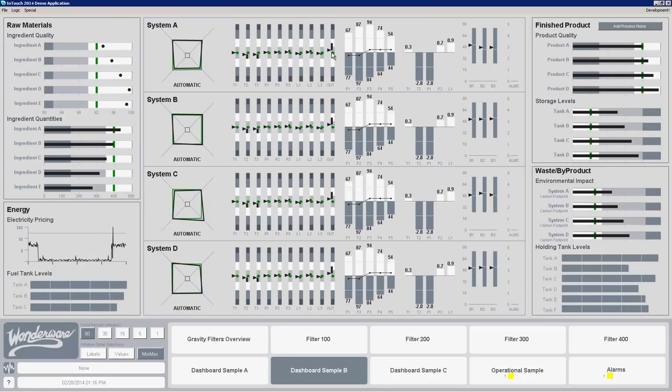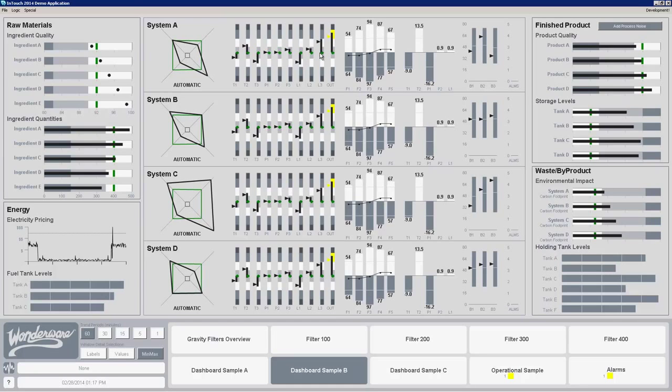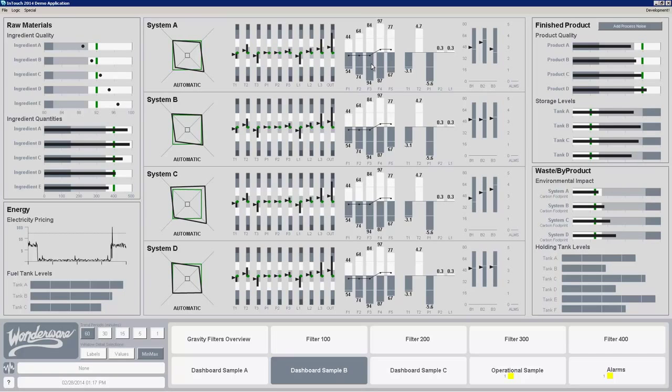What I can see here is my current set point, my current value, my optimal operating range, my alarm limits low and high, and my critical shutdown limits low and high. So I can quickly assess if this thing's going outside of expectation. Here in this gain-loss chart, I'm showing things that may be going in and things that may be coming out. So maybe flows. I may see if I've got negative or positive flows into a system, but there are different ways to use this visualization.